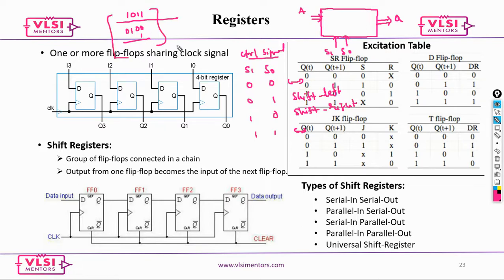So during that time, with this universal shift register, you invert all the data, so all data would be inverted. Okay, so depending on the control signal, the universal shift register would let you design whatever operation you wanted to carry out. So maybe you can go back and give it a try: design a universal shift register where 0 0 just sends out the data normally.